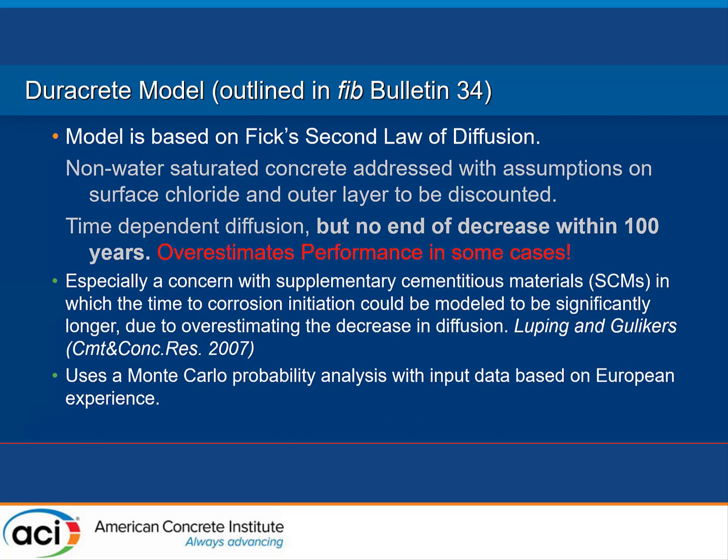The DuraCrete model, which is outlined in the fib Bulletin, is also based on Fick's second law of diffusion. Non-water saturated concrete is addressed with assumptions on surface chloride and outer layer to be discounted. Basically, you take off a little bit of the surface layer to account for the wicking. Time-dependent diffusion, but no end of decrease within 100 years.